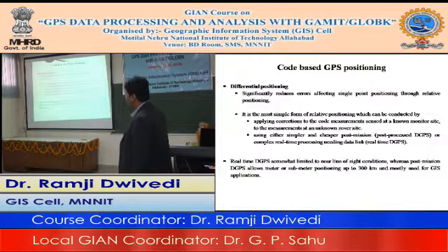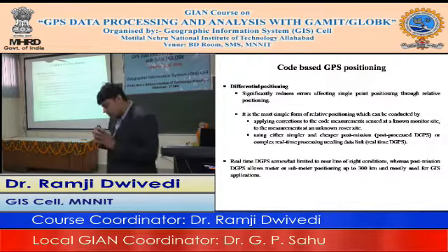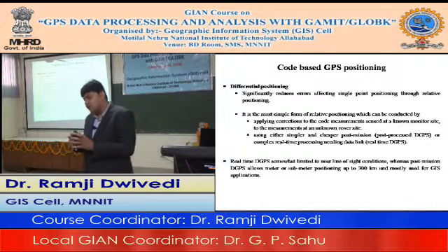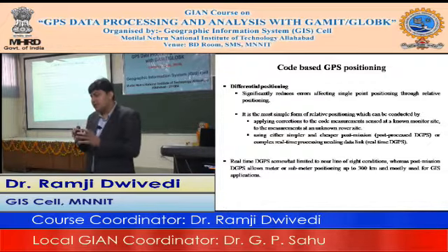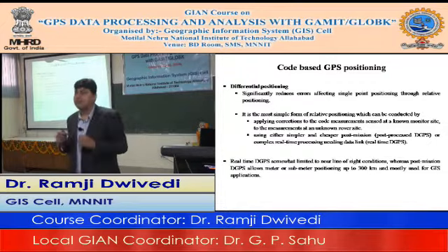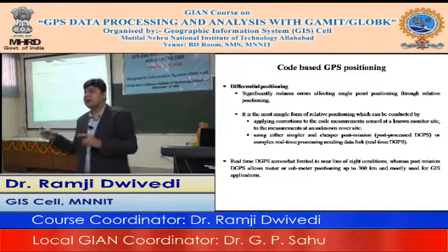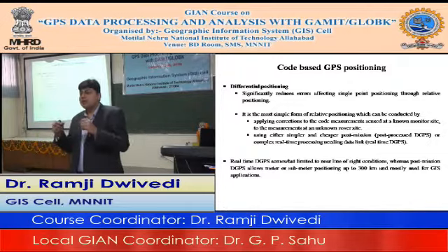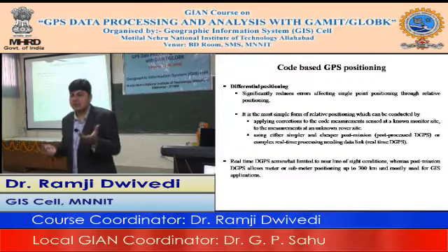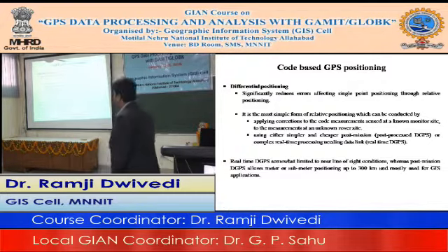Obviously for differential positioning, DGPS means differential. We have to make sure that our baseline is well within that limit, so that the corrections we apply at the rover station give the relevant precision in the position estimate of the rover. If we go beyond that baseline limit, we don't consider the further higher order terms in the ionospheric terms, so we cannot be sure whether the estimates of the rover position are good or not.